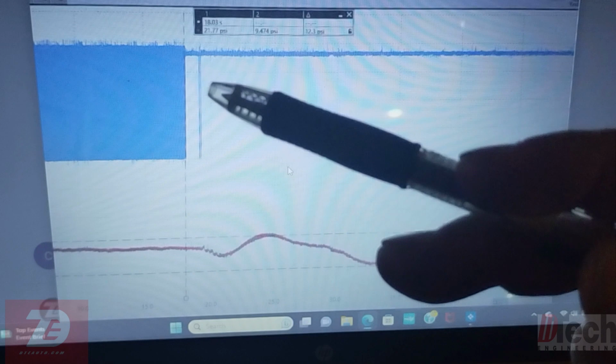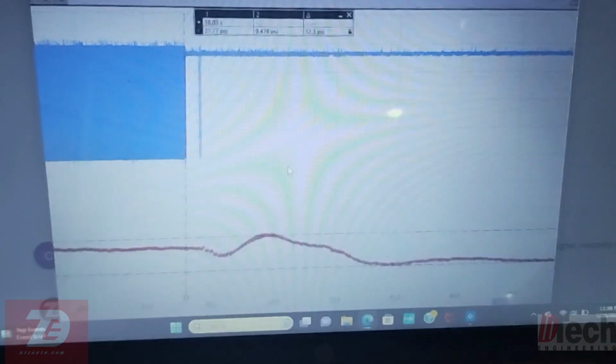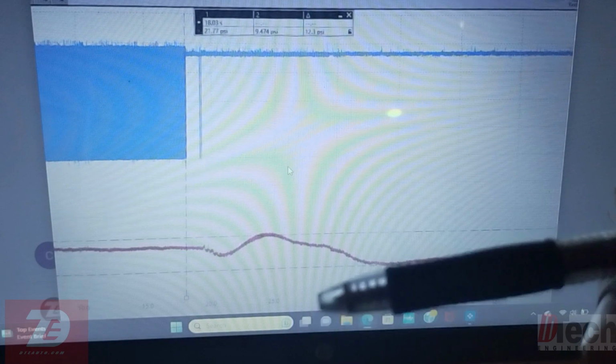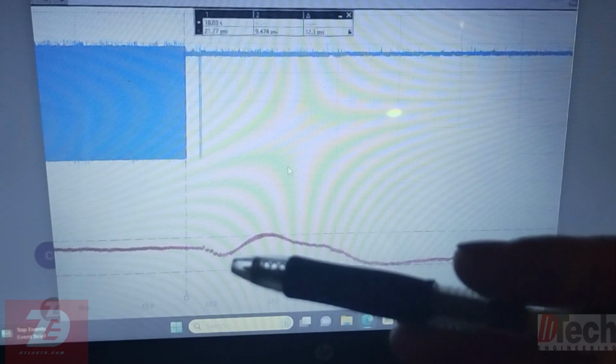And we do see that happen. So we shut off control because the DME goes kind of into safety mode, because at this point the pressure was already way too low for the DME's happiness, that it cuts off control of the valve.